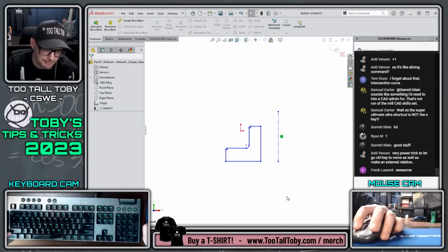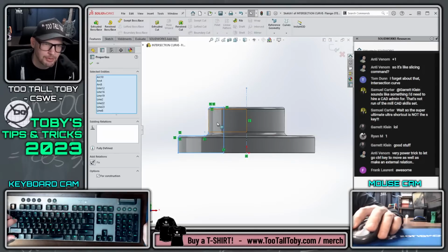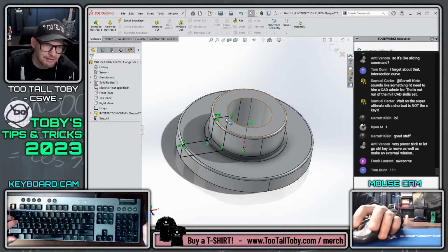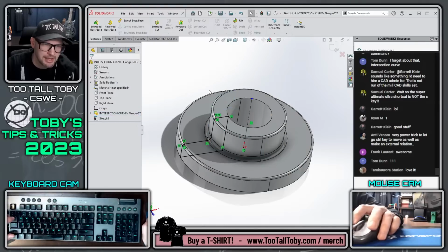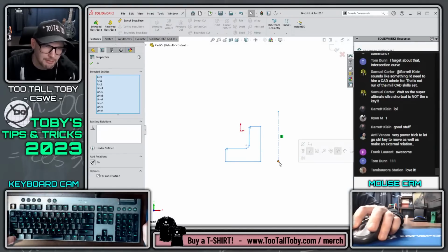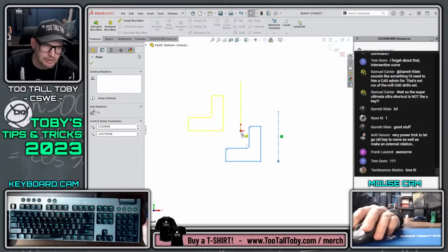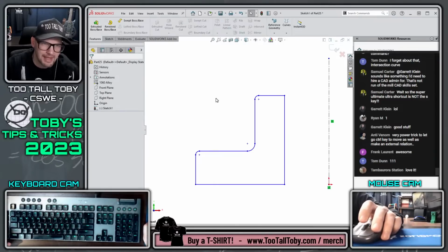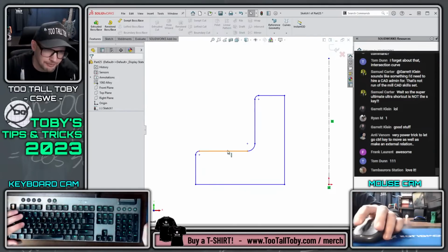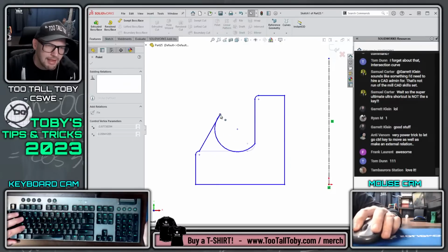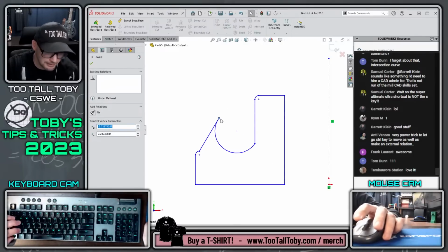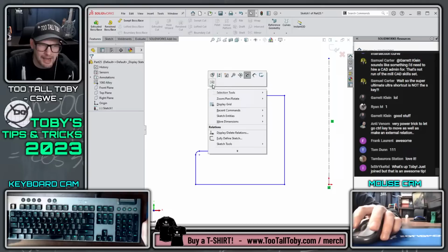Window select this geometry. I started out here in this imported part. I basically traced everything that was at the intersection of that plane and brought it into this part here. Now I'm going to hold control, drag, let go of control, drop. That gives me a sketch, but this sketch is not fully defined. Obviously, it's all blue, and even the sketch relationships are not defined. Well, we can right mouse button in the background and choose fully defined sketch.